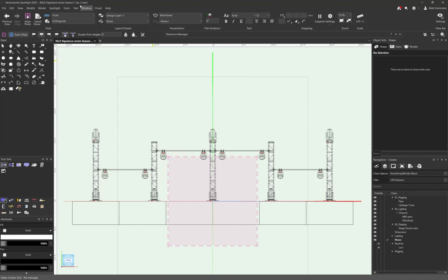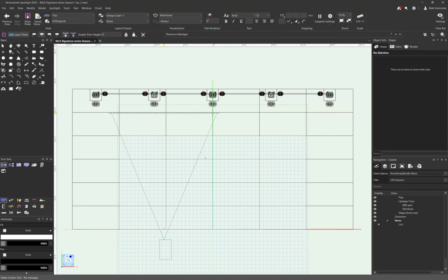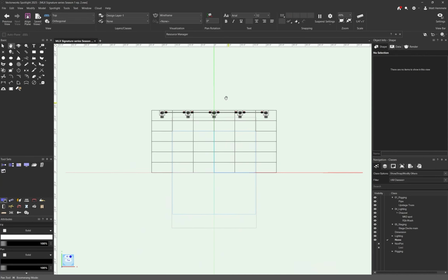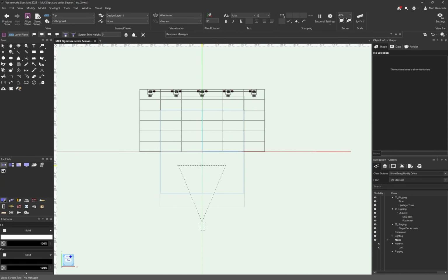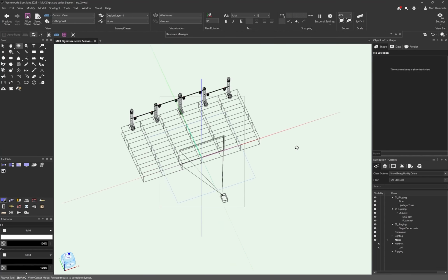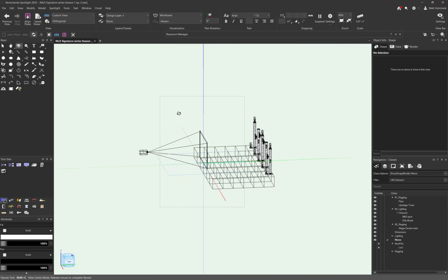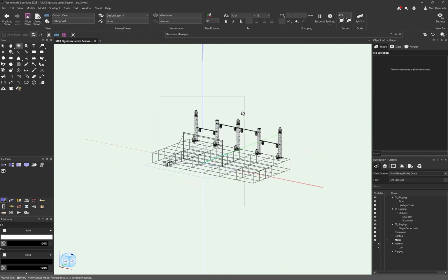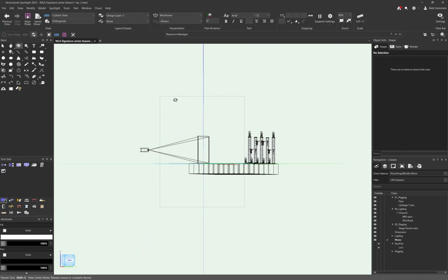And we're gonna go to our top plane. What you can see is it's going to show you basically the cone of projection, the screen and the projector. And again, here's our 0. I want to click and then double click to place it, or click again to place it. So we have basically a cone of projection and then our projector.